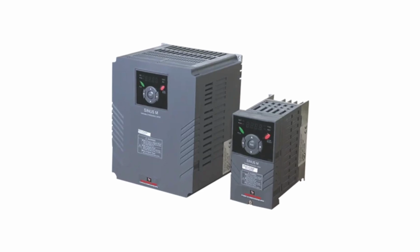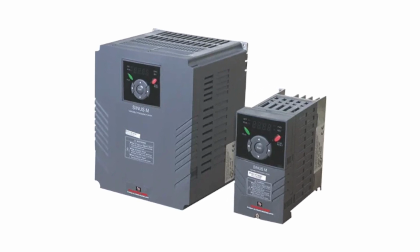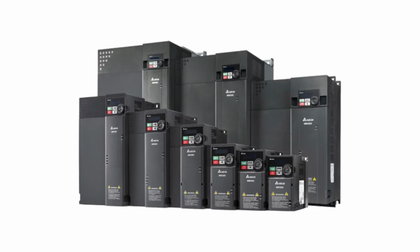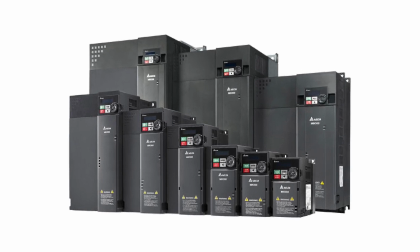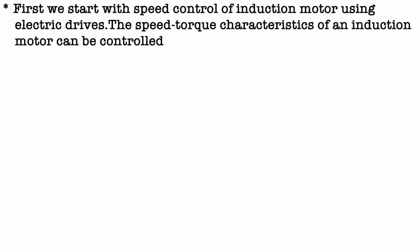AC drive is also called variable frequency drive or variable speed drive or adjustable speed drive. AC drive is used to control speed and torque of an AC motor by varying the frequency and voltage applied to the motor. First, we start with speed control of induction motor using electrical drives.